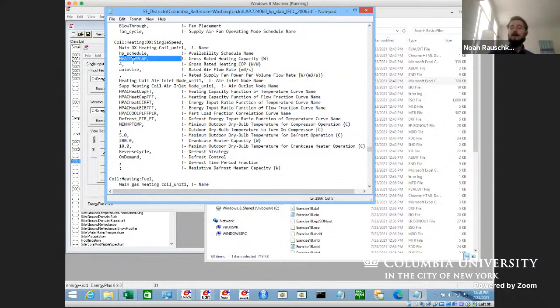I've got heat pump cap, and I can load this as a text document in R, do a search and replace of heat pump cap with 5 or 500 or 5,000, and then using a command line interface, run that IDF. That's how I did the ASHRAE paper, where I was running dozens and dozens of EnergyPlus models, all with slightly different parameters.